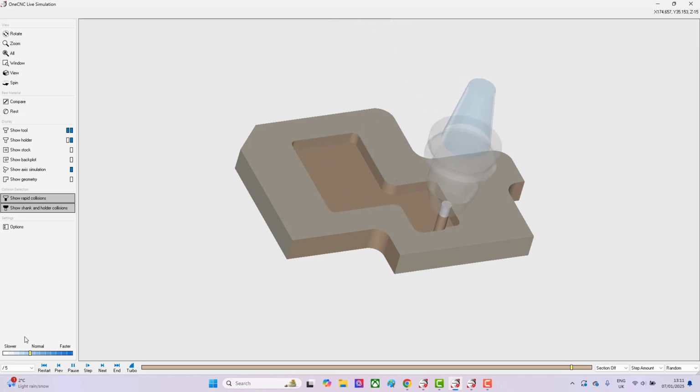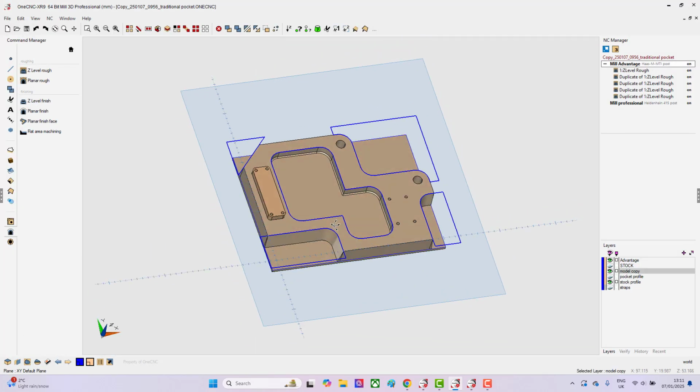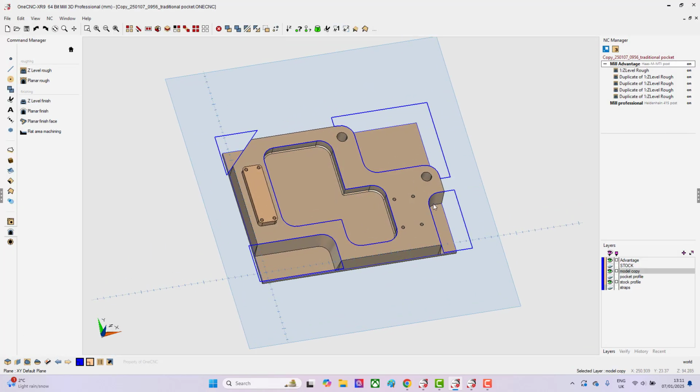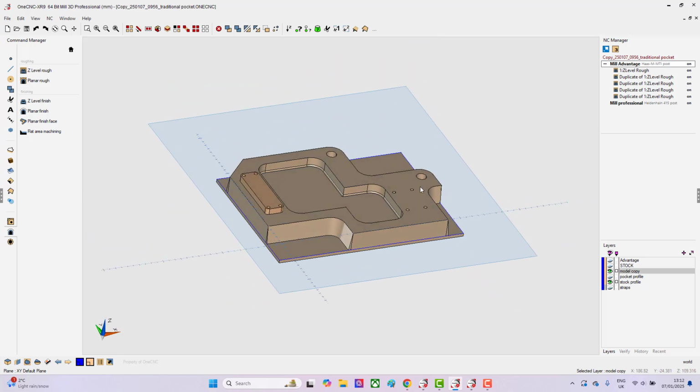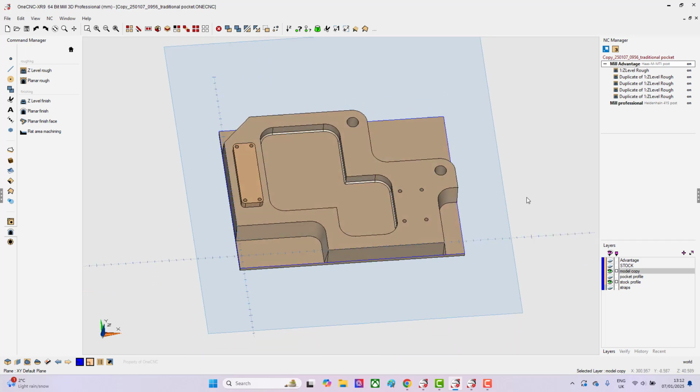So we've had to perform quite a few operations to get the software to do what we want it to do. And this is where one of the big advantages of using Professional comes in. So we can turn off the Advantage profiles, and all we need in Expert is the main profile of the billet. Because the 4 edges of this part are identical to the boundary size, it will ignore these 4 options.